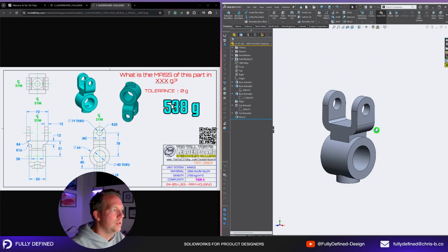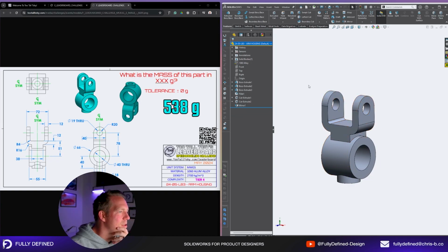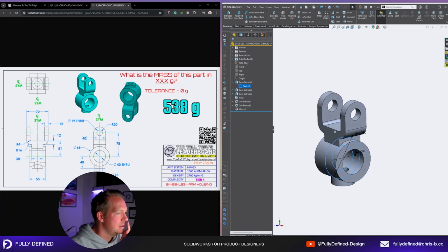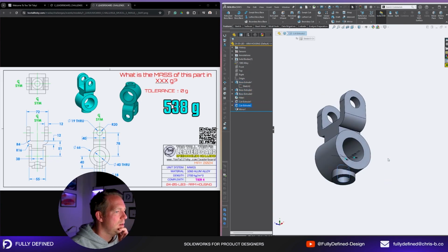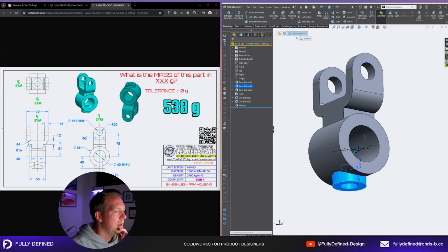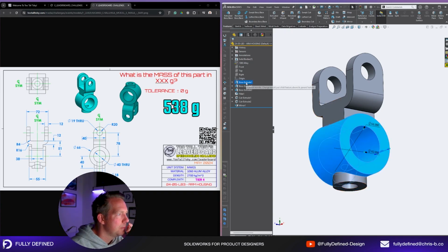All right, so first attempt, not too bad. But you can see I've got 7 features, so we want to tidy that up again. This sketch stays, and at that stage it stays. Because I'm either doing this sketch first or this sketch first. What I want to try and do is get rid of doing this hole. Now the way that I did that extrude, I don't want to have to do that bit there, because I don't want to have to do that one offset. If I did that first, everything else could just be built off that, and maybe that's a better solution.